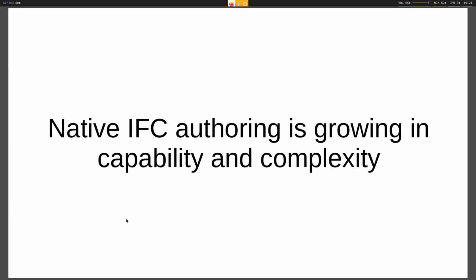And it's not just the growth. The nature of these technologies is very different to traditional BIM. These new software typically will start reading partial IFC data, not whole things, or writing or changing existing portions of IFC data. And this nature of software is very different. It's not captured by the current MVD-based certification scope. And if we don't find a way to certify these things, we cannot guarantee that the interoperability still works.